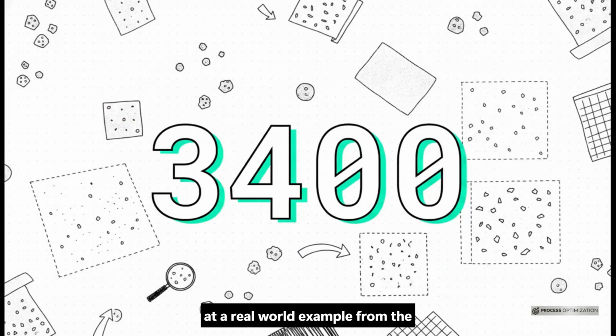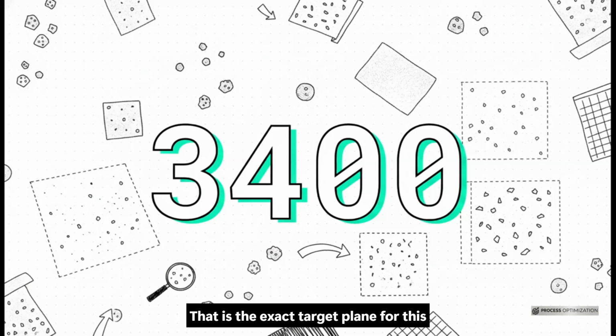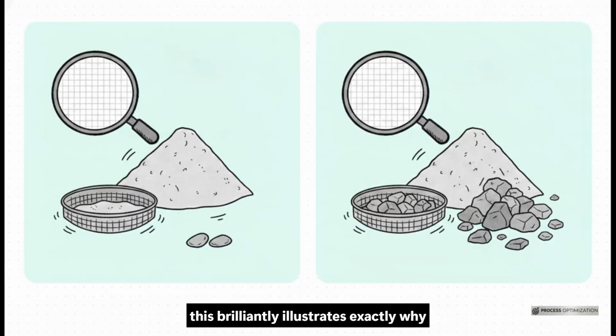Let's look at a real-world example from the source data to really lock this concept in. 3,400 square centimeters per gram. I just want to pause for a second to let the sheer microscopic scale of that target surface area sink in. That is the exact target Blaine for this specific grade of cement. And this brilliantly illustrates exactly why Blaine alone is never enough.